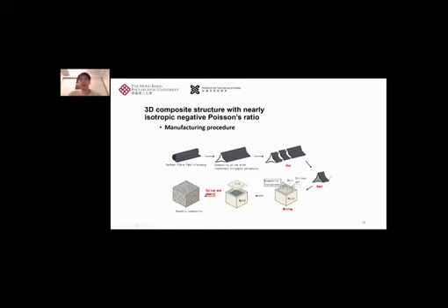The sealing is quite necessary, because if we don't seal the two ends of this reentrant prism and leave it open, when we add in the silicon gel, the silicon gel will get into the inclusion, into the prism, which makes the composite just become one silicon composite with some carbon fiber plate. It will not create this reentrant triangle structure inside the matrix to create the auxetic effect. So after we seal it, we put it into the mold with the silicon gel, then just leave it to cure to get this composite.